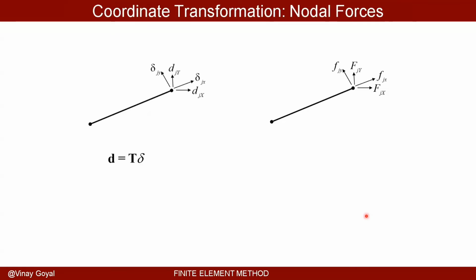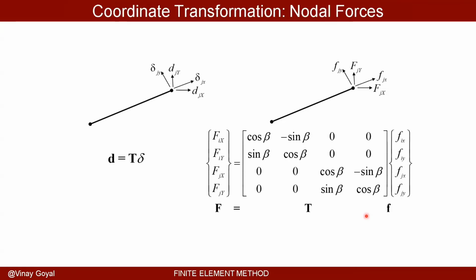We can apply that idea to forces too. I think everybody agrees that there's a local force in that element that's oriented this way, and a force perpendicular to that element in the local orientation system, small f. But in the global orientation system, I instead have f bold, f uppercase, and I can relate that in a very similar fashion to how I did it here for deflections.